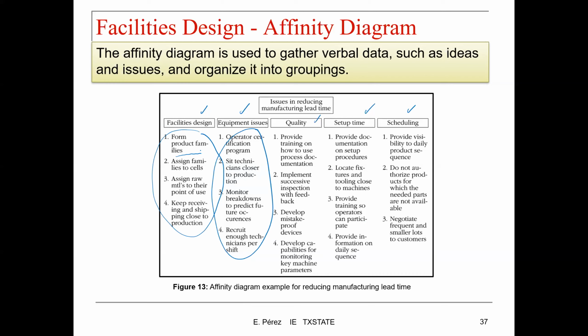And then they have their key products, such as the Galaxy and the Galaxy Note. So those by themselves can be categorized as a separate family. So the process of producing those cell phones is different. If we can separate them as families, then things such as setups can be reduced. We can produce this family first, and then we can do the setup and produce the next family. So maybe in this example that's not available. So that's a key thing that we can do.